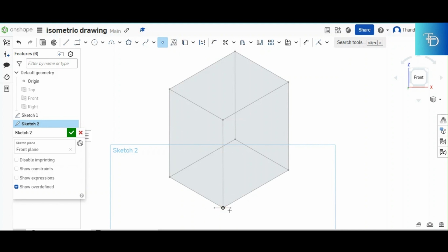At this area, this is the lowest point. At this side, that is the lowest point. So which means if you were to mark your 25 millimeters at this line right here, you mark it from that point upwards. Here, you mark it from the center point upwards. Right there, you mark it from that corner upwards. So you mark your 25 right there, 25 millimeters.